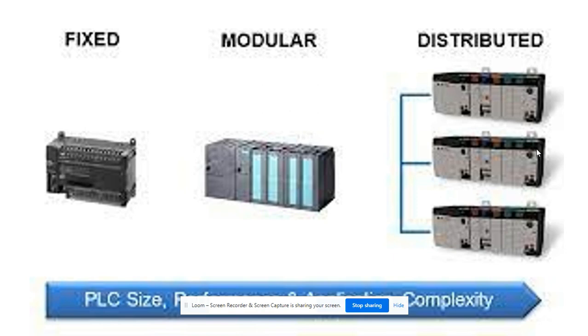There's the fixed PLC, where all the modules are combined intrinsically into one, like you can see in that diagram. The second one is modular, where all modules of the PLC like the input, power supply, and CPU are distinctively separated as shown in that diagram. You can separate them, but they are in one place. And the third type is the distributed programmable logic controller.